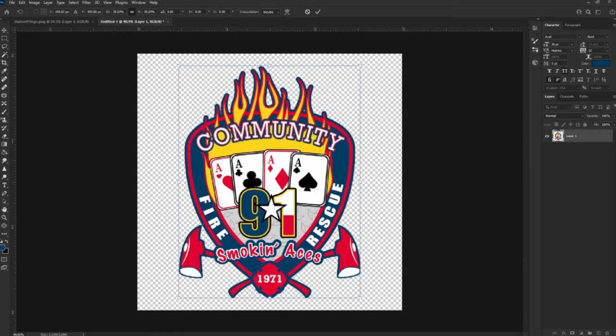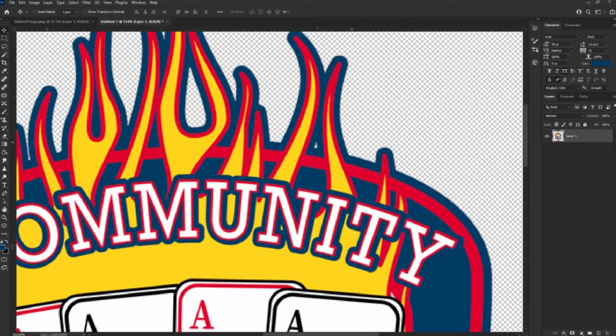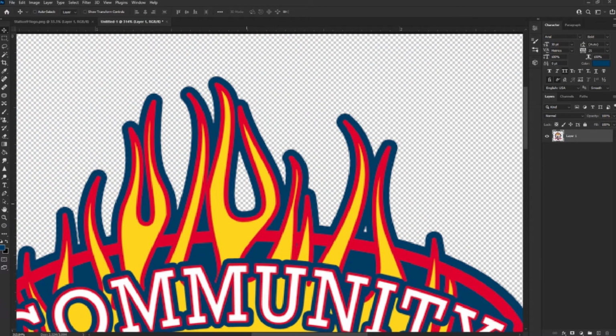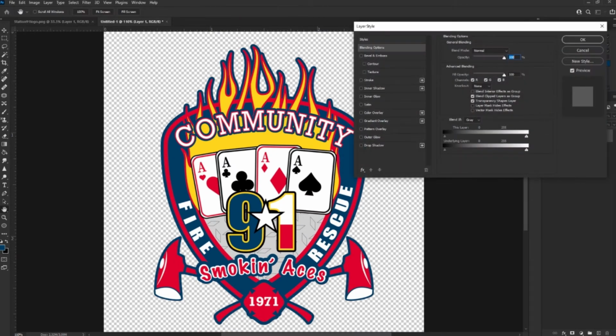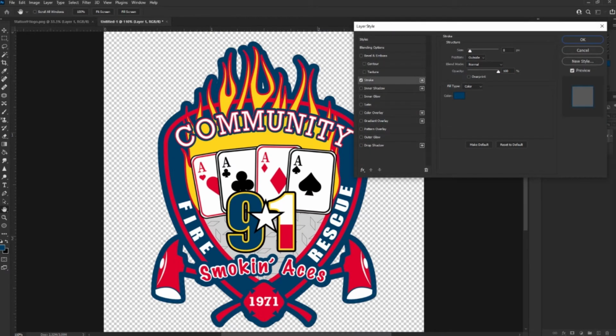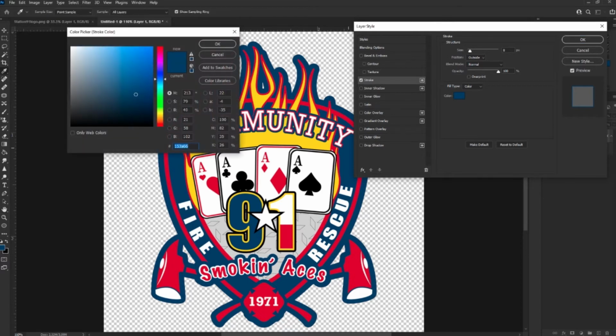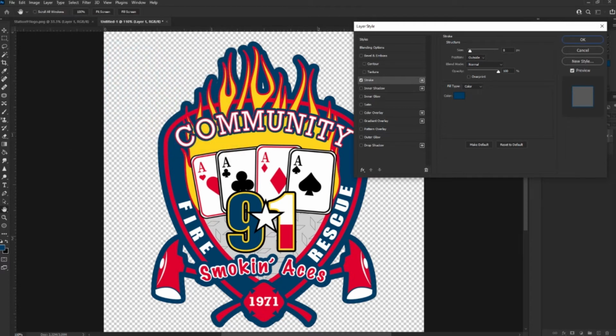All right, so here I am. Now I know that I want my cut to go around here, but I don't necessarily want my machine to cut into this little hole or down into all these different grooves, mostly because it's just going to take too much time, and I need to make a lot of these. So what I'm going to do is double click on this layer and add a stroke. Now this one happened to already be that color because I've been working on this, but if you needed to add a stroke, you go in here and choose your selector tool, and I'm going to play with this outside border. So I'm going to choose one that I kind of like.